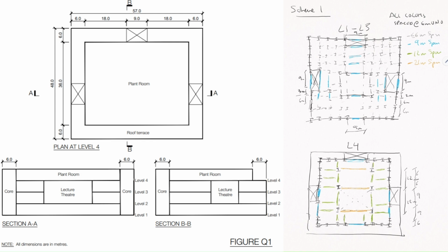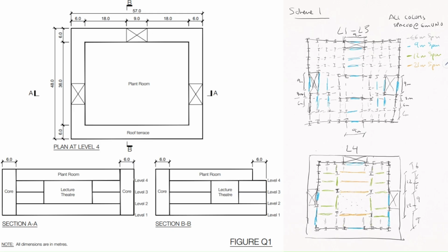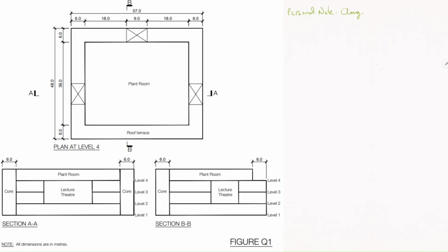Now here is where I notice the column arrangement that I was drawing, especially with those internal roof columns in the plant room, would be better as a concrete structure, because all the vertical structure that I was adding in here, basically the columns, were all under compression. And what that means is it's ideal to have concrete under compression.